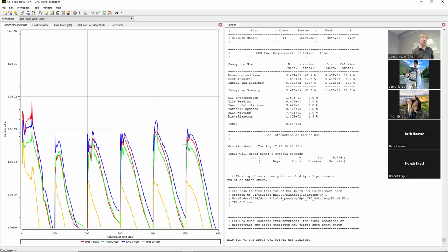For the problem, I don't know if anyone's looked at it yet. You have to do on-design and off-design cases. So I'd say plus or minus Mach 0.5 from whatever your design case is, and then plus or minus 5 degrees. If you're at the Mach 5 case, I think you can just jump straight to plus or minus 5 degrees and be okay. At Mach 8, I don't know. When it starts to get a little unstable, if you do smaller increments, it's typically safer.